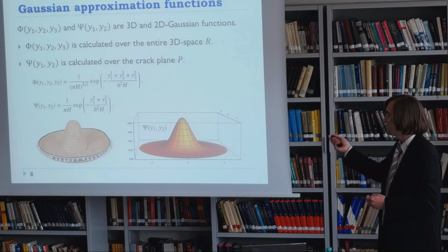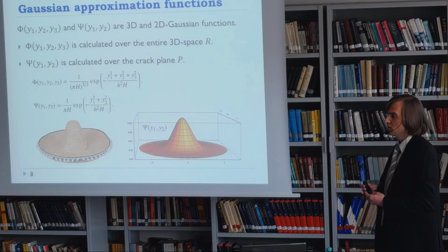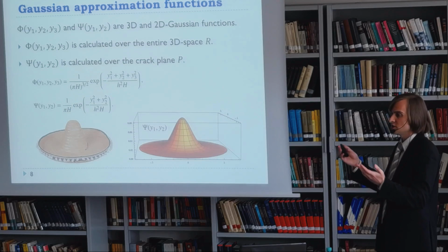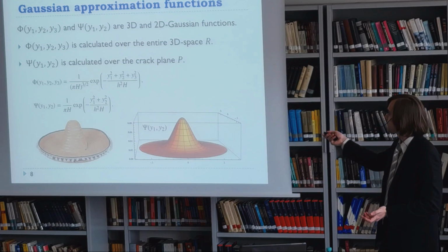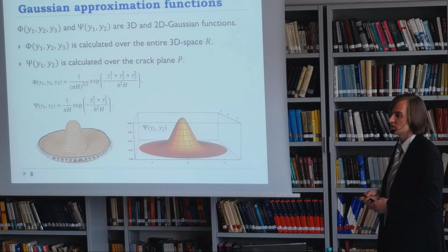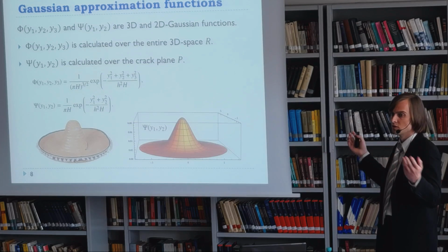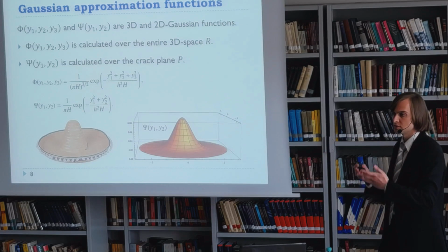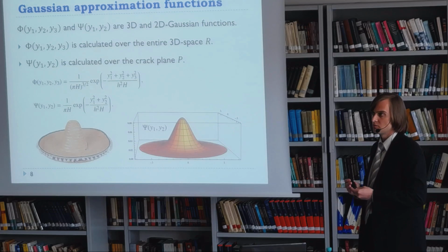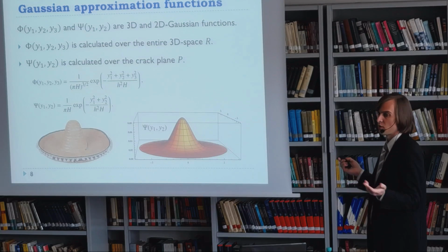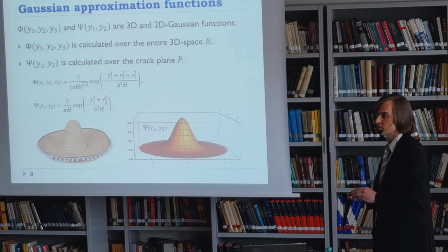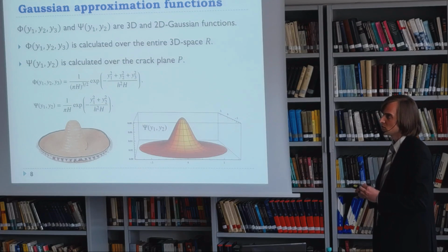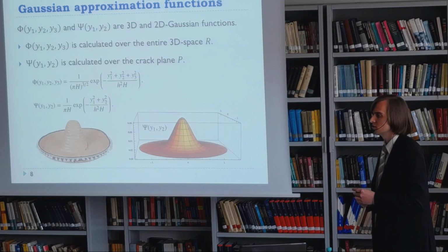Actually, for this method, if you have a homogenization problem, we don't need any boundary condition at all for our RVE, the representative volume element. But this is a finite problem, of finite volumes, of finite cracks. For a semi-infinite crack, it would present some issues. We would need to introduce fictitious boundary conditions, because we cannot simulate it in a straightforward way.